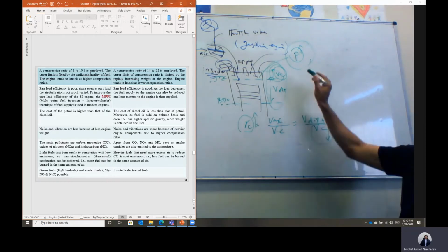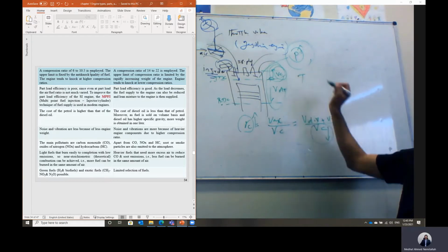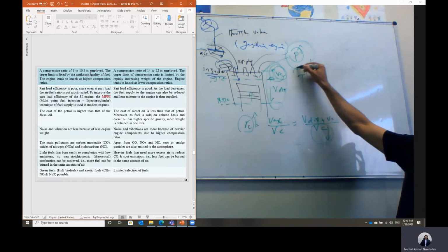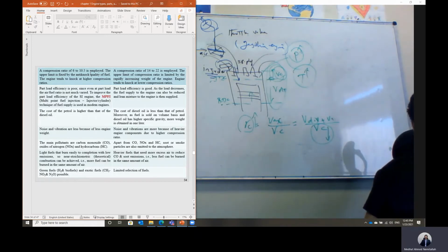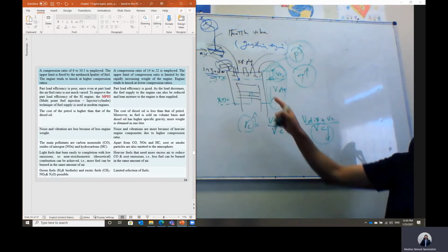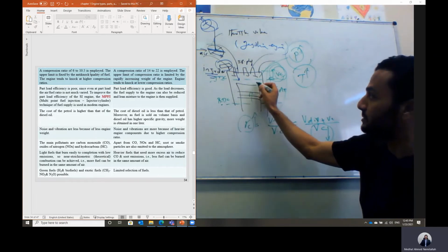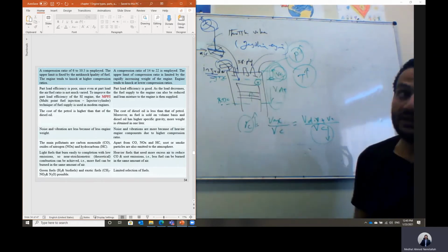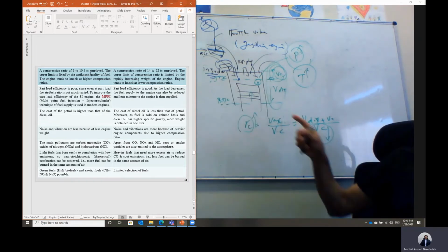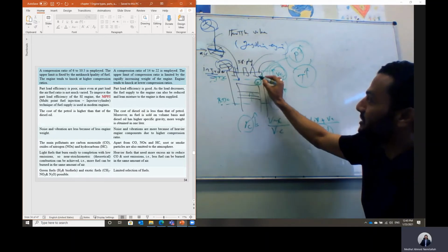Because in this case we cannot approach a very high pressure. As the pressure increases during the compression stroke while the piston is moving up, the temperature will also increase. But if it exceeds the self-ignition temperature of the fuel, then before the piston reaches top dead center, the fuel may self-ignite at some point close to the corner, because close to the corner the gases get hotter. So this will be self-ignition, an explosion.